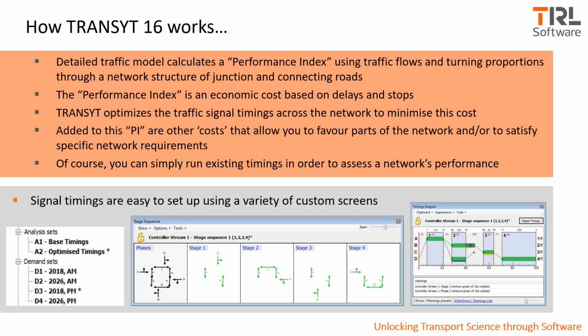Here are a few of the screens just to show you what some parts of TRANSYT look like. These screens there, the timing diagram on the right and the stage sequence diagram in the middle, very interactive. You can change the stage sequence quite readily by dragging and dropping items. Timings, you can extend stage lengths or add in phase delays quite readily through the diagram itself. So very interactive user interface indeed. So let's move on.